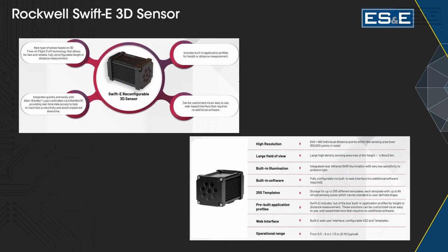That's good. And the last step was your cutouts, right? Yeah. So this is a 3D sensor. It's actually an Allen Bradley 3D sensor. Okay. So this is going to be used to verify the cutouts are there, make sure they're the correct shape. Since it's an Allen Bradley as well, it's easily integratable to the Allen Bradley PLCs. Okay. Well, good. So it just shows up as another device in the tree there. It does. And you can have all types of shapes and different templates and everything like that. I think it'd be good for your application. Okay. All right. That sounds good.